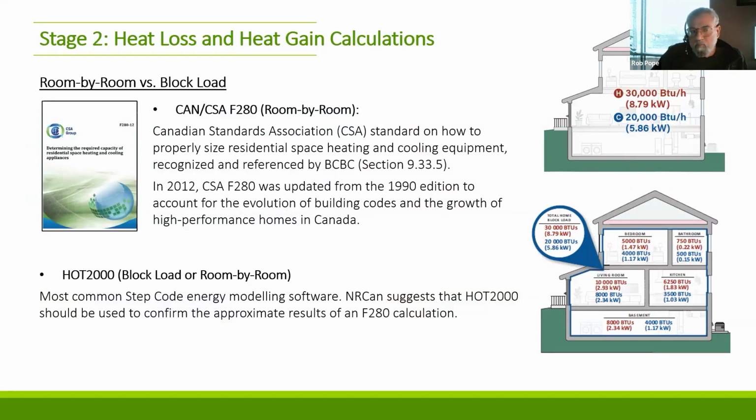The other way to do it is a block load, just the whole house. And that would be a recommendation for a retrofit, for example. You don't have to. It's nice if you can, if you've got the resource, time, and the money to do it, to do load calculation broken down room by room in a retrofit, but block load is adequate. But in new construction, because you're designing the delivery of the heat and cooling, you really need to do room by room.